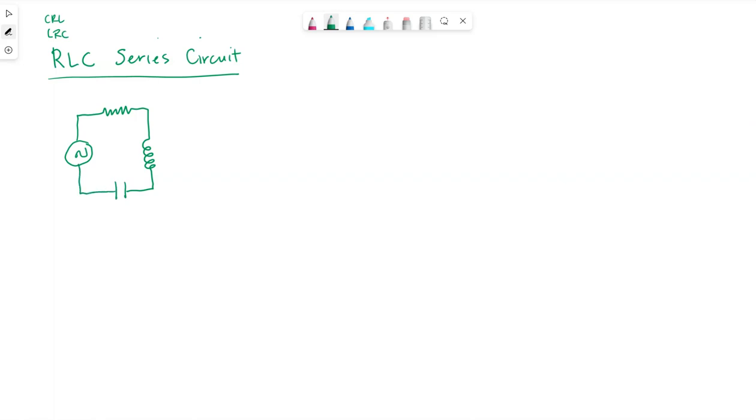All in series is what we're going to look at. The order in which these three are connected doesn't matter. What matters is that they are in series. Now, that's not the only way they can be connected, but we are specifically going to look at the equations and the phasor diagram to represent them connected in series. So our source voltage is alternating with time.